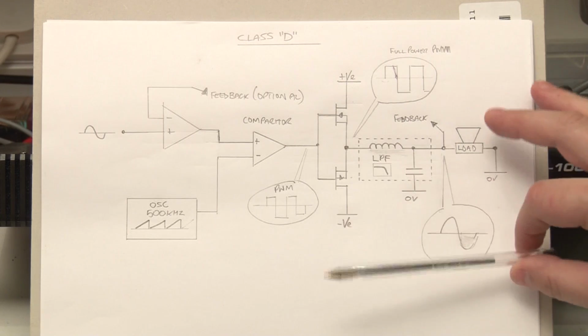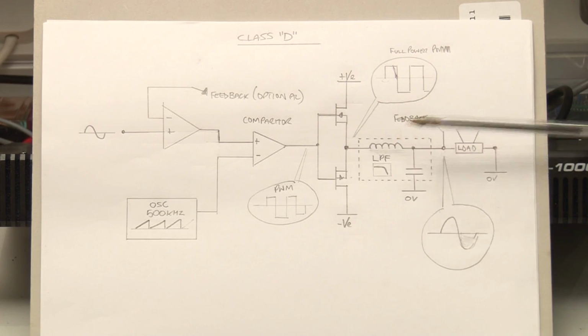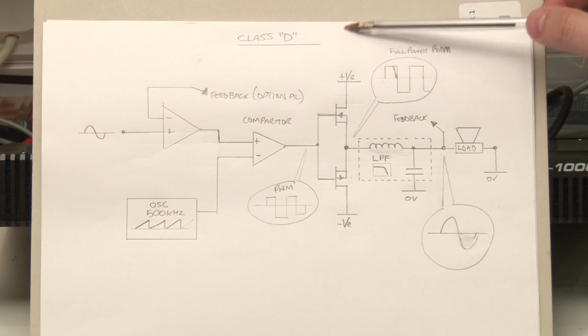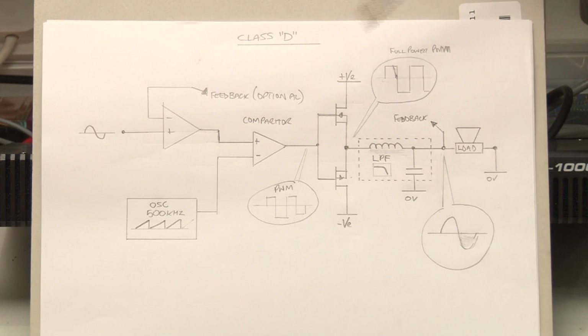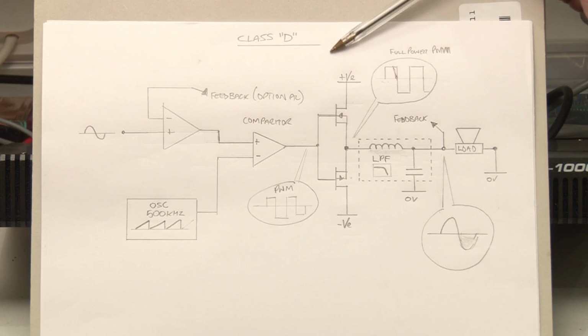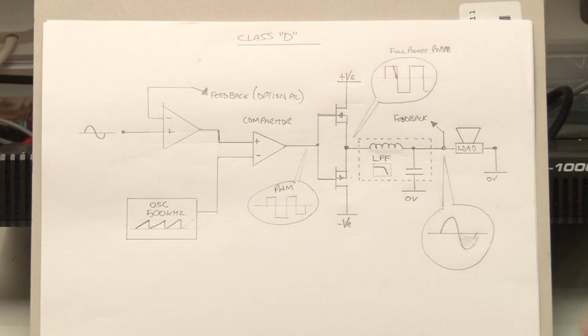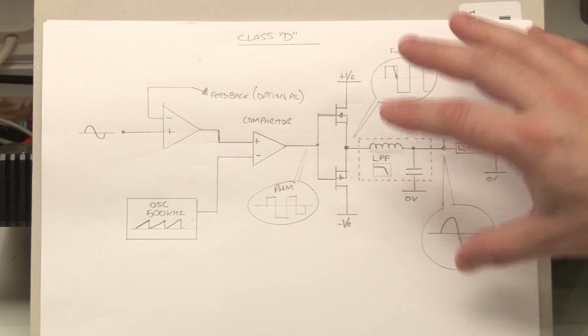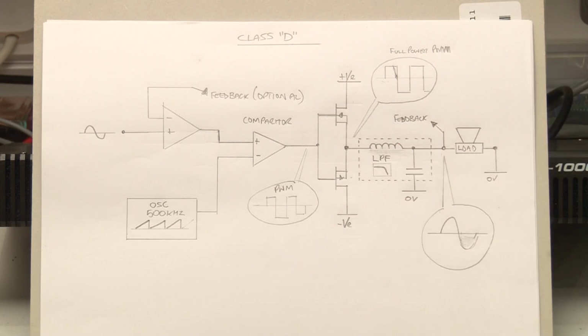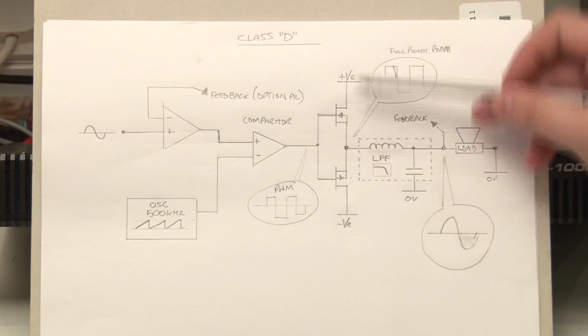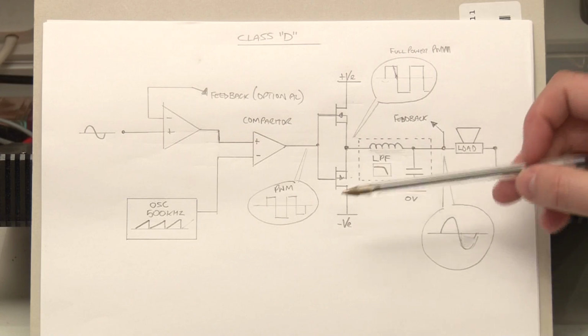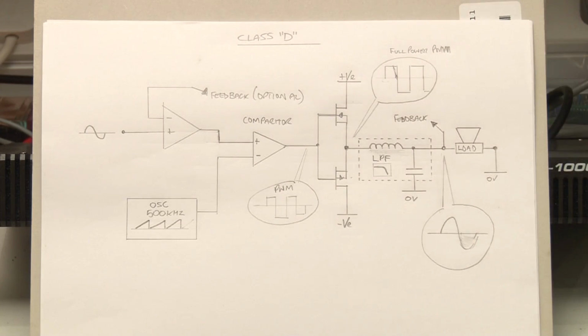So if you want really good quality audio, you typically don't see Class D amplifiers delivering that in hi-fi. Where you do find Class D amplifiers a lot, in hi-fi and also in many other systems, is in things like subwoofers. It's very common to see a physically small Class D amplifier delivering a couple of 100 watts into a subwoofer, often just single IC based as well, because they're switches, they're not linear devices. So that's where you see them. Anyway, that's the basic principle.